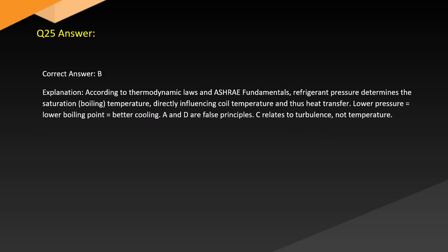Answer. Correct answer: B. Explanation. According to thermodynamic laws and ASHRAE fundamentals, refrigerant pressure determines the saturation boiling temperature, directly influencing coil temperature and thus heat transfer. Low pressure equals low boiling point equals better cooling. A and D are false principles. C relates to turbulence, not temperature.